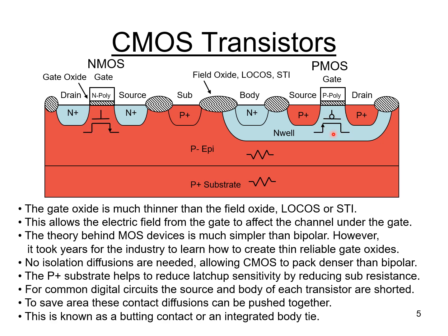There's actually a very thin oxide underneath the gate on each of these transistors. And that gate oxide is sort of the whole secret to MOS transistors. You needed a very thin gate oxide because these transistors use a field effect to create a channel underneath the gate connecting the source and drain together. So this is the basic theory of MOS: you use an electric field to create a conducting channel that shorts your source and drain together.